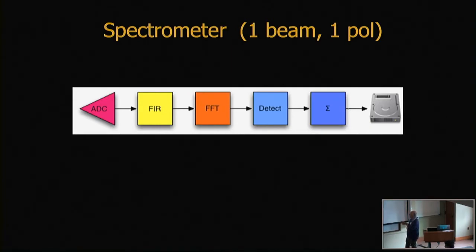What Deepti was talking about was fitting sine waves and cosine waves, because we don't know the phase. And then this detect thing: the fitting can go negative or positive, so the detection is squaring the data, so you get just positive signals. We're measuring the power, voltage squared. Is that what your question is?